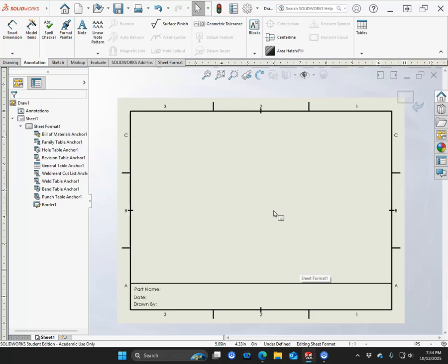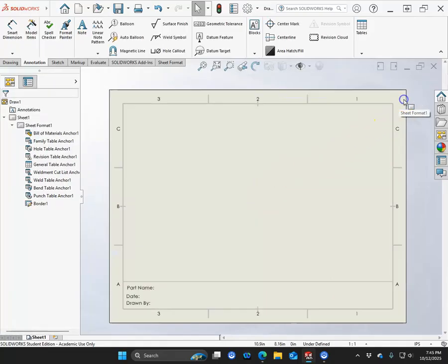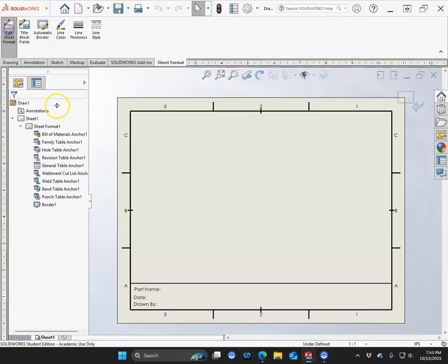The other drawing templates and sheet formats that I've created have typically been taking one of the existing ones, pulling out all of its notes and its data, but we're relying on all of those relations up front. So just for this first video, we're going to accept the sheet format. Everything kind of goes into the background now. None of these are editable. So at this point, I would have to decide what items I want to put in this group to be able to edit.